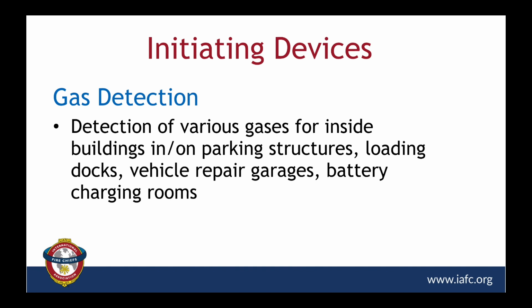Secondly, carbon monoxide, nitrogen dioxide, or propane detection is required many times in warehouse loading docks that have gas, diesel, or propane powered forklifts, as well as in vehicle repair garages or in enclosed parking garages. Hydrogen detection is often required in battery charging rooms. And carbon dioxide detection is required in rooms without mechanical ventilation systems that have more than 100 pounds of carbon dioxide that is used in beverage dispensing equipment.